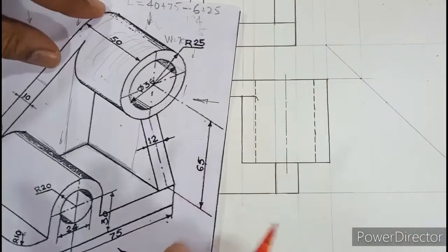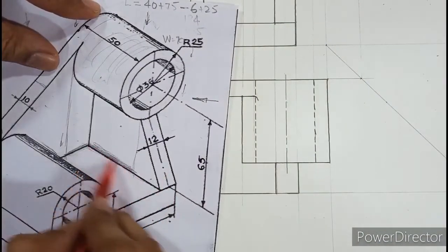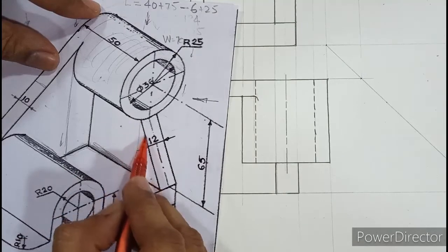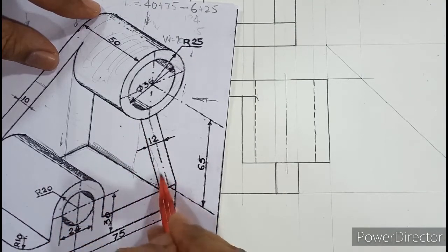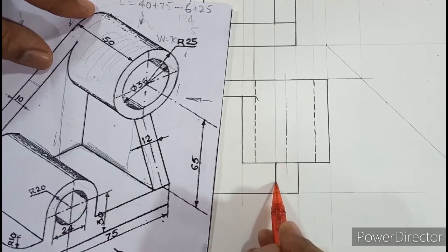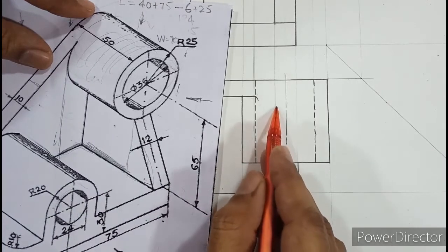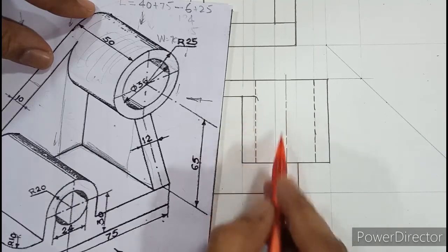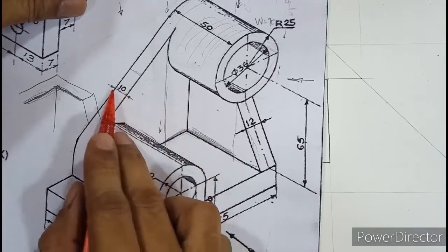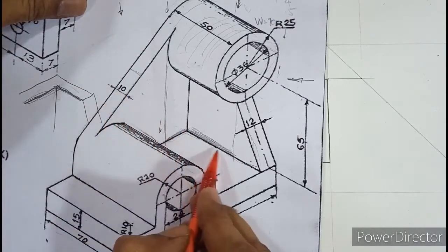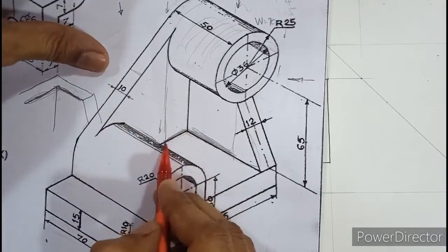If you look at the first part, look at this edge, what I am talking about. It is exactly in line with this rib, and that to the left side of the edge. So this edge, you need to extend hidden. That is what I want to say. But till where? This hidden line you need to extend leaving 10 from behind. Once you leave 10 from behind, you need to take an L-shaped turn.